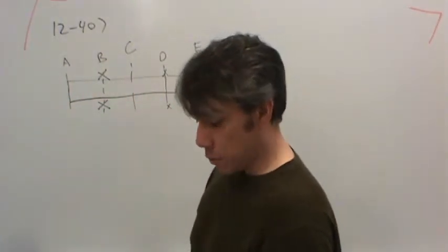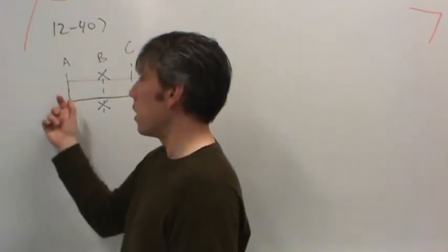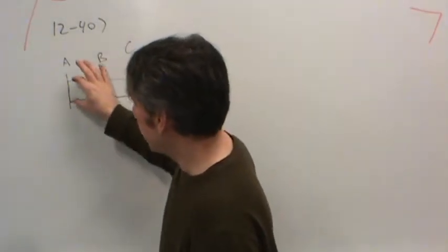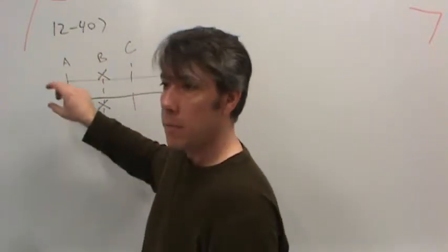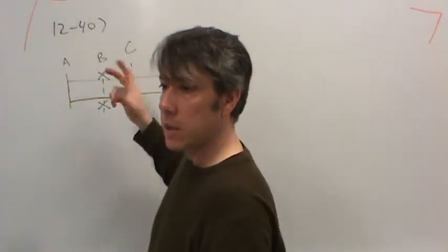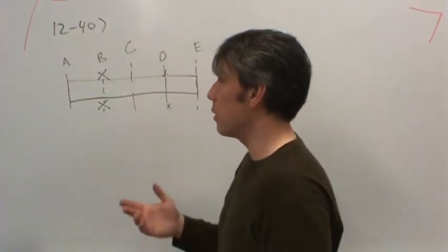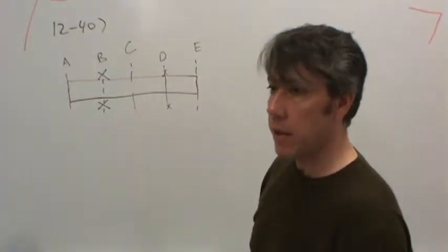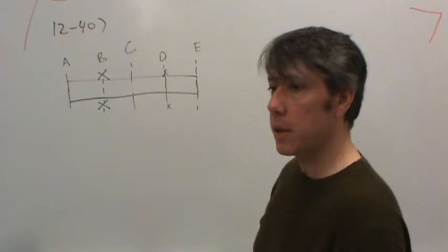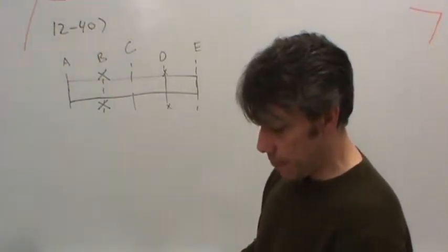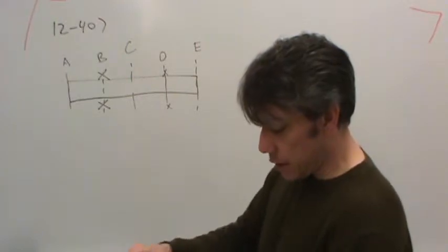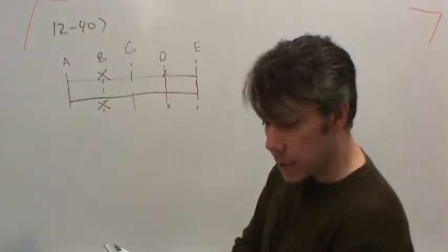Now for practical purposes, since A has to be slid onto the shaft, what you would typically do is make the size on this side of A be slightly smaller just so that it's easy to slide it on. Usually on a shaft like this, you wouldn't have a press fit. You'd have keys or retaining hooks or something to lock it to the shaft. But I drew all of this because I wanted to make some notes.